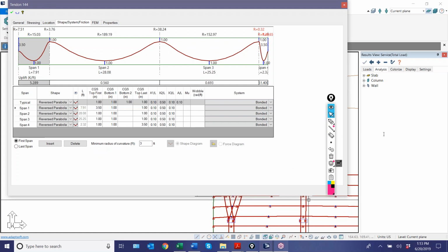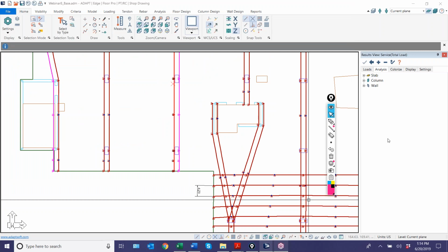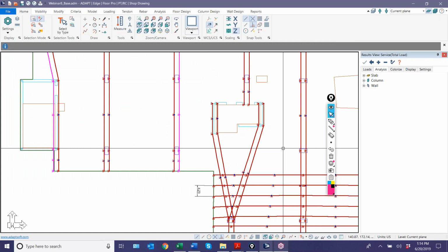I mean, typically for a slab on ground that is maybe residential, it depends on where you're at. In the U.S., almost all slab on grounds are unbonded. If SOG is what you're referring to, for slab on ground residential design, even commercial, like for a warehouse, many times here it's unbonded.